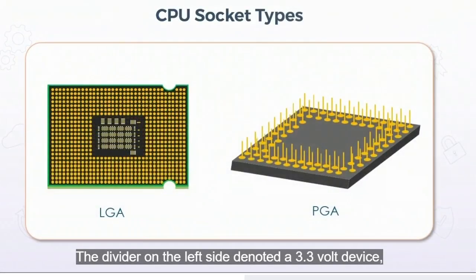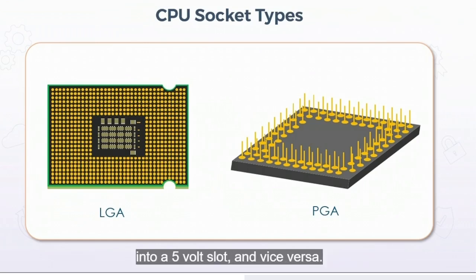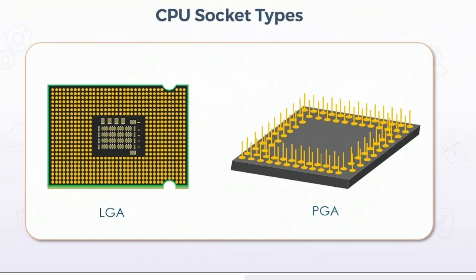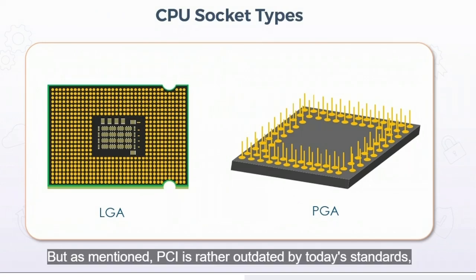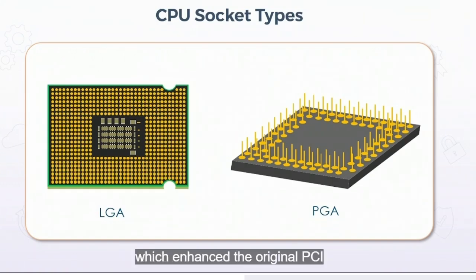So among the replaceable or upgradable chips and socket types, the land grid array uses flat metal contacts on the underside of the chip, which then simply rest on the corresponding contacts of the socket, hence the term land of LGA. You more or less just place the chip into the socket, and the contacts of the chip land on the contacts of the socket. Then there is typically some kind of a bracket or a brace that closes over the chip to hold it securely in place, and the processor itself is keyed with small notches to prevent incorrect orientation.